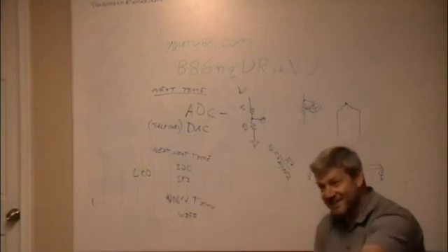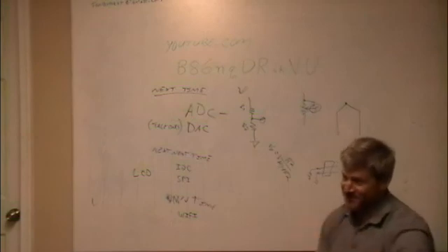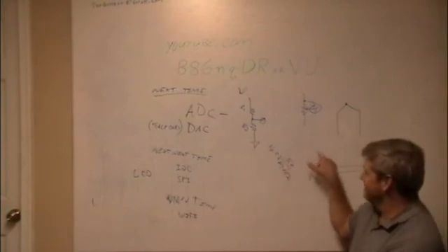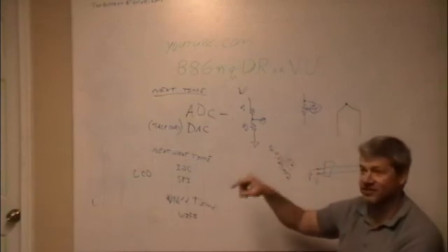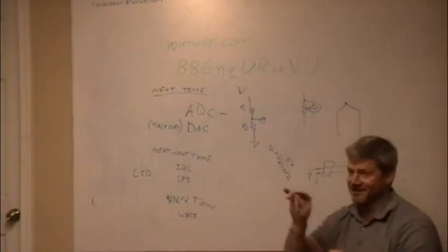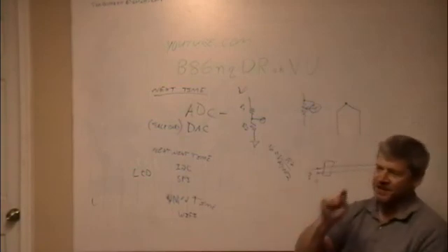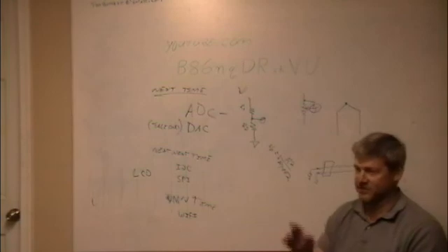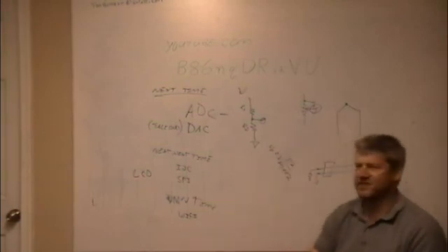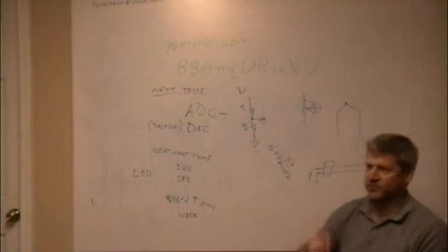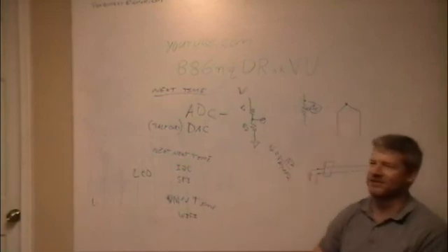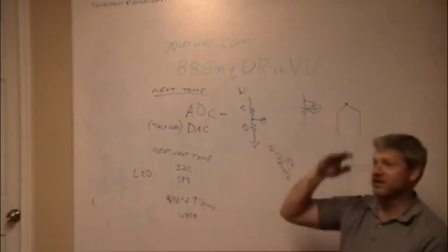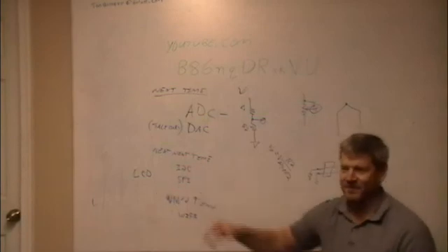So the nice thing is, if you go to Auber Instruments and you buy one of these things, it's got all this built into it. Instead of you having to go figure out the PID curves and all this on your own, you can tune them right there. And you set up a time temperature table. At 0 seconds, this is my assumed start temperature. At 15 seconds in, I want it to go to this temperature, and it'll start ramping up to that temperature. And at 30 seconds in, I give it the same temperature again, and it stabilizes, and it'll try to hold it there. And it's already made.